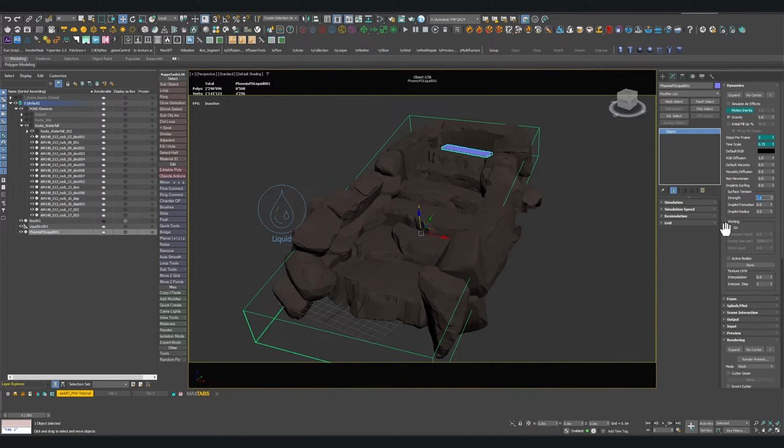It is just holding the particles together or binding them stronger together, so you get a flattened or smoother water surface or liquid surface, and it is not creating those wild splashes and stuff. So I'm going to set that for now to 0.05 because that is pretty sensitive.